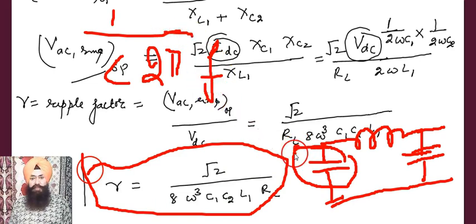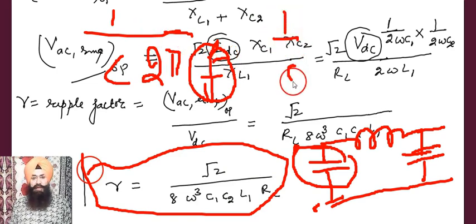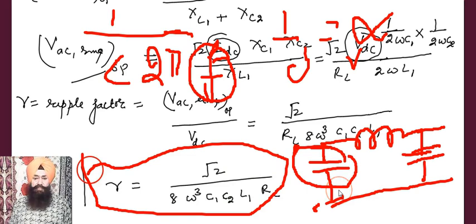So when the input comes here, which has AC and DC values, for DC the frequency is 0 and 1 over 0 means infinite. So the capacitor offers infinite reactance to DC. So DC cannot pass through the capacitor, right? So DC cannot pass. So DC flows now to the inductor.